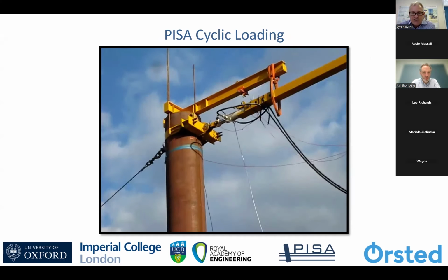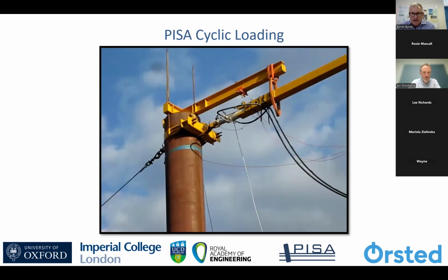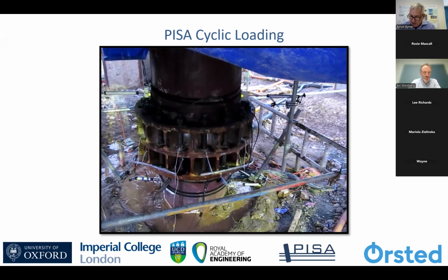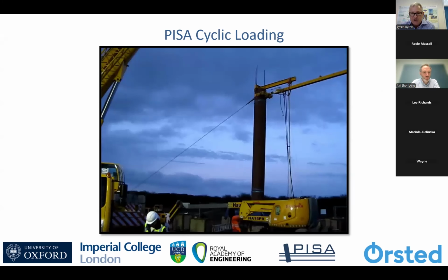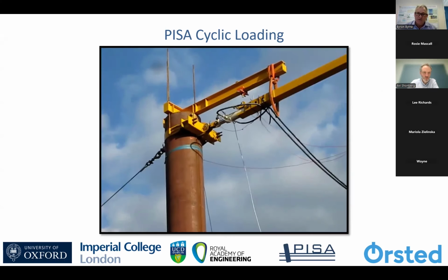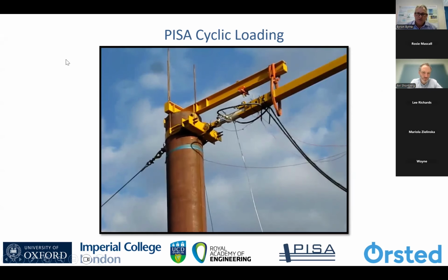And you can see the actuator just moving away under load control, very well controlled activities. We've got lots of instrumentation. And in these tests, we were able to apply cycling over 4 or 5 days, so many tens of thousands of cycles, to try to understand the impact of the loading. So this is very important data. Because of the design setup, the loading applied can only be one way, going from zero to a maximum load. A more complicated design can give you a two-way loading.